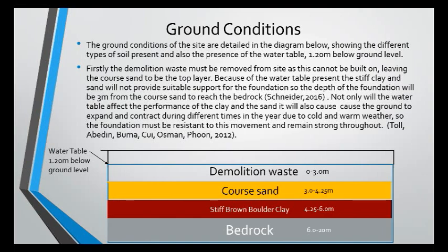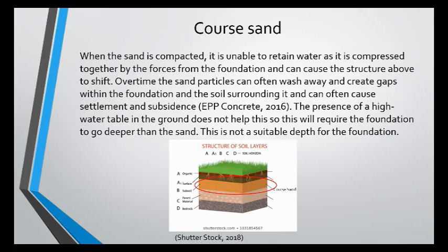When evaluating the ground conditions, it was clear that the demolition waste cannot be built on and therefore must be excavated and removed. There is also a water table at 1.2 meters below ground level, which will affect the performance of the sand and the clay.